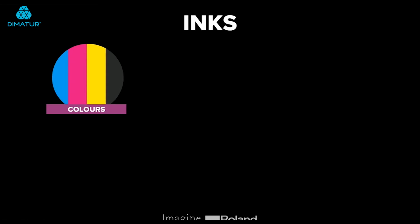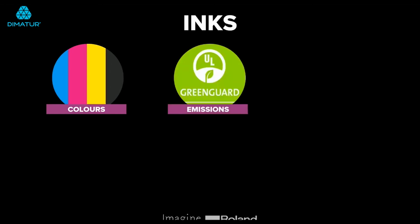If you're particularly color focused, however, and have customers that need to hit particular Pantone colors, then you may want to consider adding additional inks in there as well. So, for example, at Roland, we offer a machine that also includes a red, an orange, and a green ink. We have others that just have orange in, for example. So, dependent on the type of printing that you're going to be doing, it's worth thinking about whether you need cyan, magenta, yellow, and black, or something else in that mix as well to help you hit those colors.